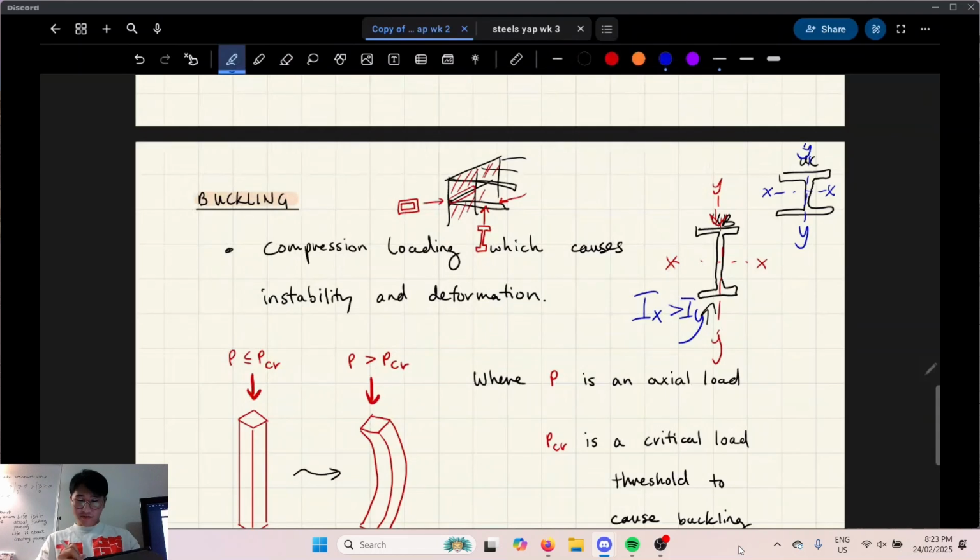They're only equal for a square hollow section. IY means it's bending sideways. So which one's stronger for the column? Still the up-down direction, but is it by the same degree? No. For an I-beam, IX is usually 10 times bigger than IY, something in that ballpark. But for these, they're more closely together, I don't know, 3 times bigger, something like that.